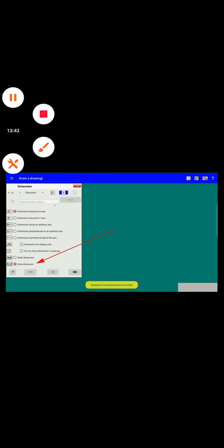First, select the type of dimension, diameter. The diameter can be specified in two ways, with a center or two extreme extension lines. We choose the option with the center. In this case, the second extension line will not be available. We indicate right away that the dimension for the hole will now be set. Although this characteristic can be specified later and even after